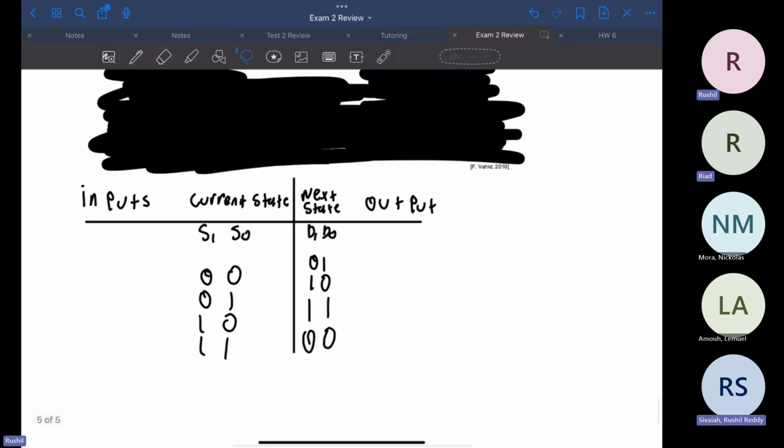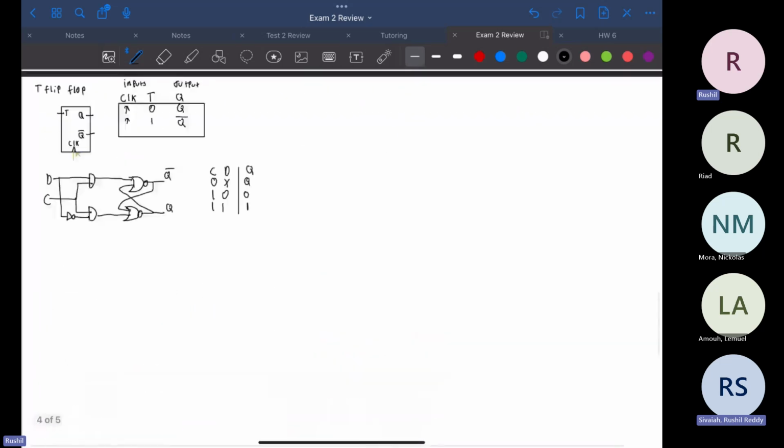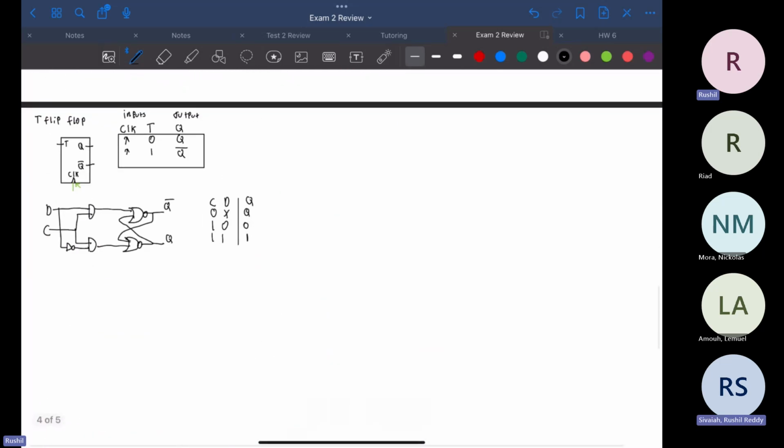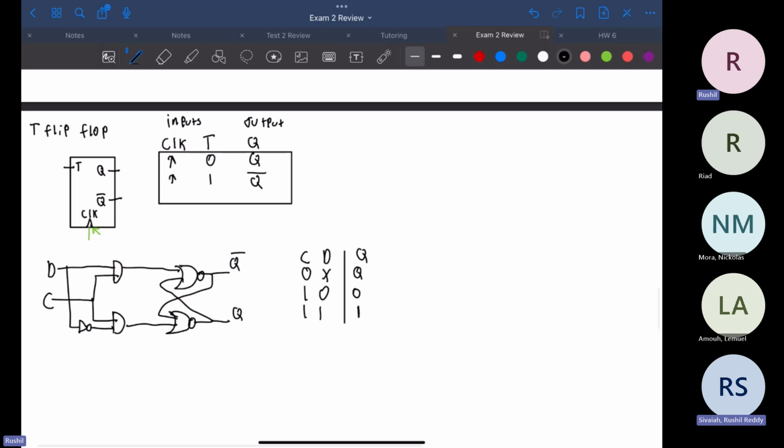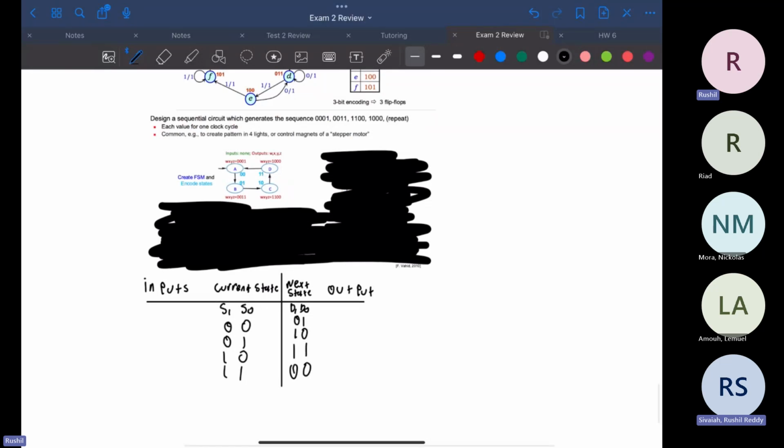I think it's easier to do it D1 and D0 instead of S star because you're going to get mixed up. If you don't get mixed up, I'll be surprised. Well, if we look here, most registers are built out of flip-flops, and the input to a flip-flop is D. So we're technically not doing the wrong thing. I don't know if that made any sense.